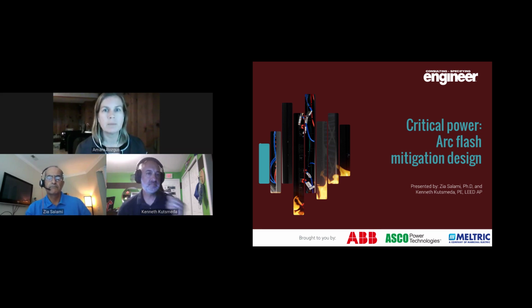Got it. Thank you. All right, Ken, this next question is for you. This is a code question. Is NFPA 70E enforceable, and is it really considered a code? So NFPA 70E is really an industry standard, so it's not enforceable. OSHA, however, is enforceable, and OSHA does quote NFPA 70E often, so it's not directly enforceable, but inspectors and so forth can enforce it through OSHA.